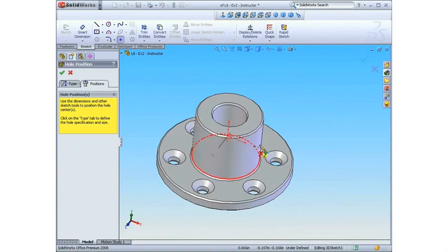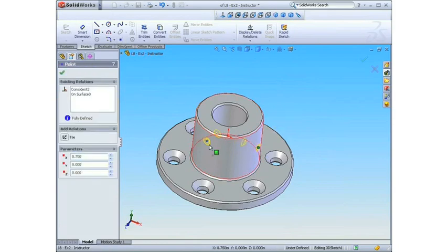So it's important that I select not the point, but the face. So I create my holes perpendicular to that face. And once I've created my two perpendicular holes to that face, I'll then press escape to get out of my point command and drag my points to be coincident to those points.